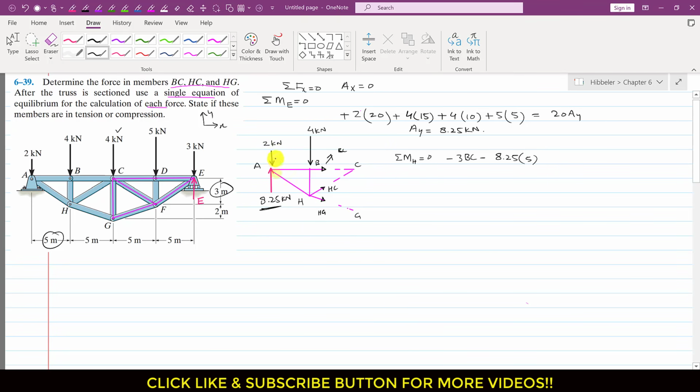Similarly, this 2 kilonewton force is producing a counterclockwise moment about point H, so I will write plus 2, and the moment arm of this 2 kilonewton force from point H is this 5 meters length, so I will multiply it with 5. And similarly, this 4 kilonewton force is passing through point H, so it will not produce a moment about point H, right? So this is equal to 0. Now we have a single equation for this single force, right? This single equation will give us one unknown force, that is the BC member force.